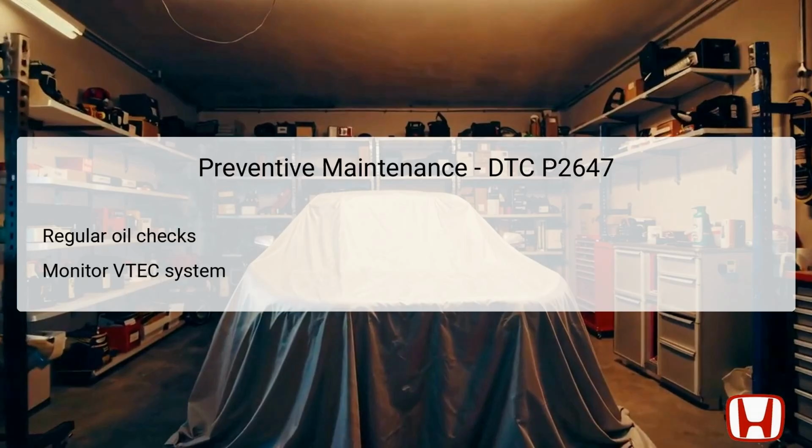To prevent the recurrence of DTC P2647 in the future, implementing routine maintenance is fundamental. Regularly checking the engine oil level ensures that the oil pressure remains within the appropriate range, thus supporting the functionality of the rocker arm oil pressure switch and the VTEC system. Additionally, monitoring the overall performance of the VTEC system can help catch any anomalies before they escalate into significant issues.